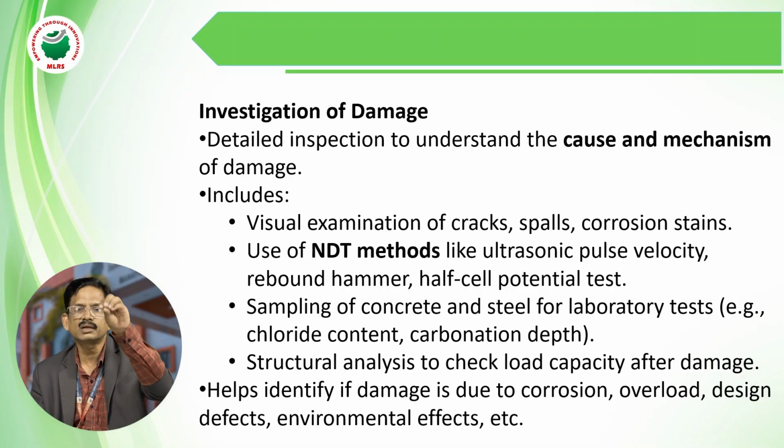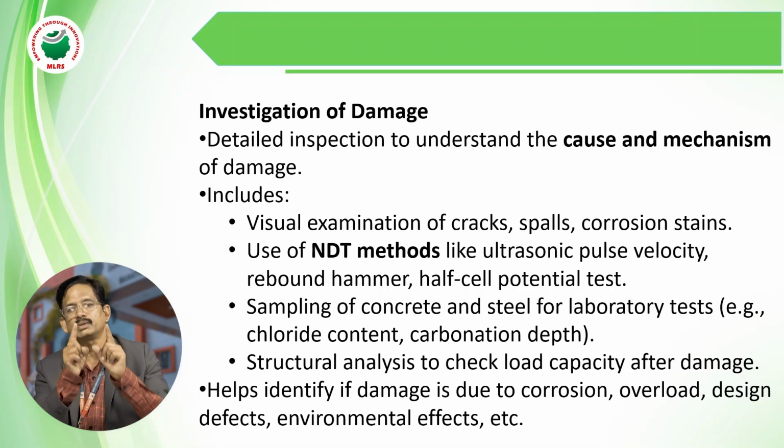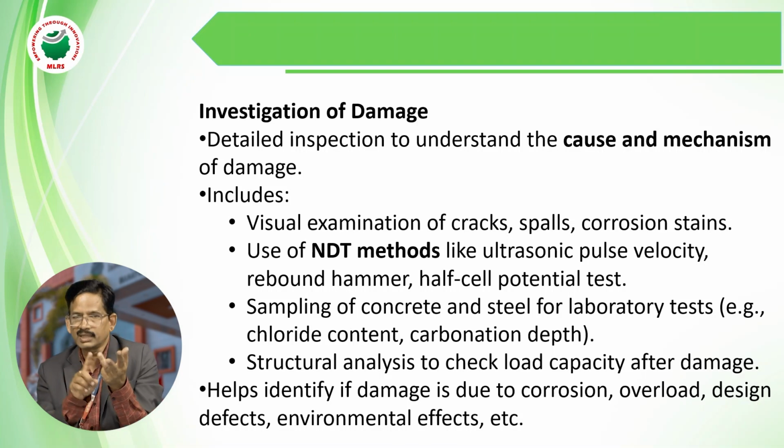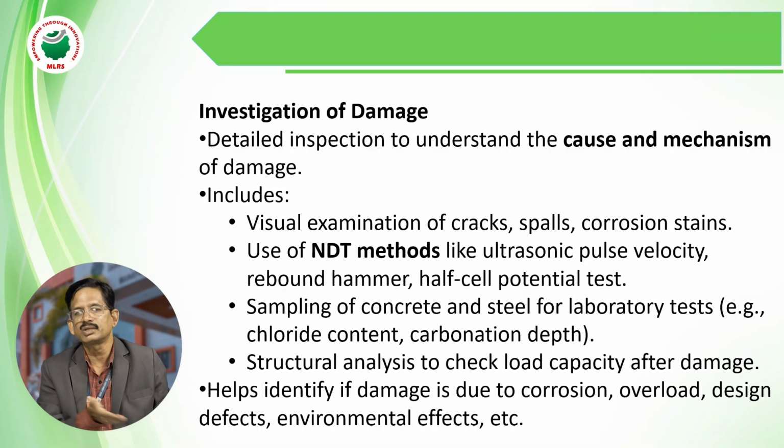Suppose you are designing a column of M40. As per the drawing, you have to verify that the column is of M40 grade. Without dismantling that column, with the help of non-destructive tests, either the ultrasonic pulse velocity or the rebound hammer, we test the particular column at the site. We have to test whether the column grade is M40 or not. In the similar way, we check the slab, the footing, and the shear wall also.